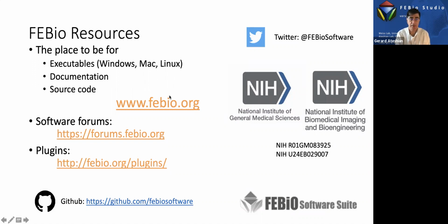We actually have an undocumented stabilizing factor that we can use. However, when we compare the results to a biased mesh, we don't get the exact same results. So it's a kind of hit or miss. You're playing with the stabilization parameter, and you can keep increasing it until you get a smooth response, but you don't know if that smooth response is correct. So that's one limitation.